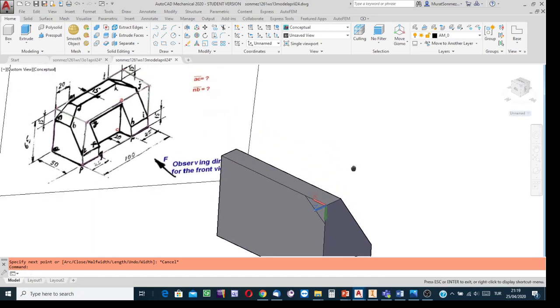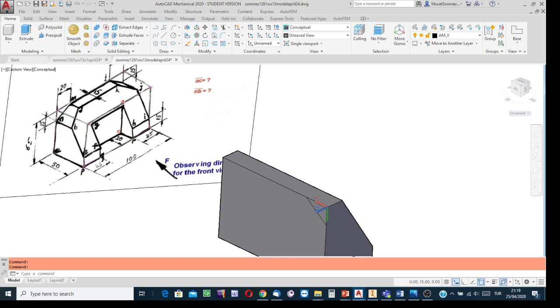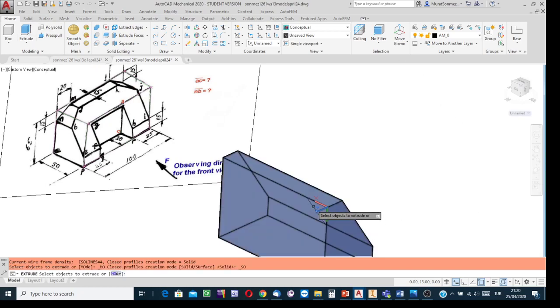The rest is extrusion process. Applying extrusion process, since we don't know NB is unknown, the thing to do is to create the triangular prism, a little bit arbitrarily in length. It should be greater than the order of NB. If I further extend the prism, I can guarantee to have the surface in the correct size. Apply extrusion process and then indicate this profile.